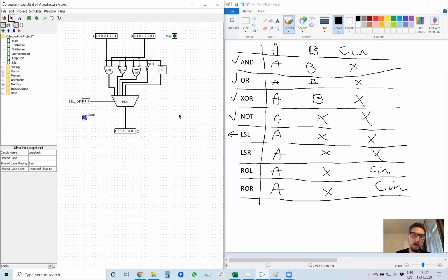So to connect it correctly, I would need to do a multiplexer, which selects between carry out values. So to make it very simple, we will put another mux for the carry out bit.